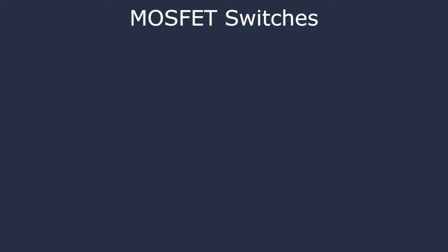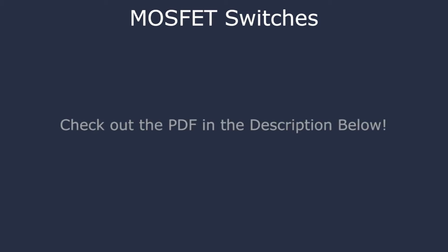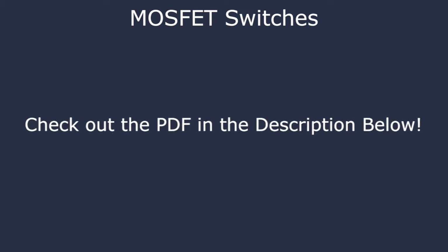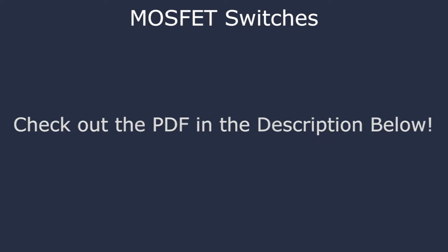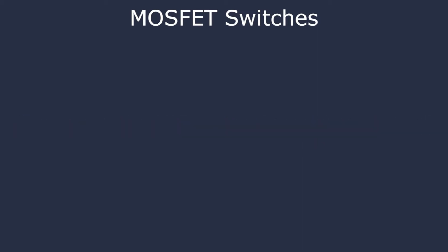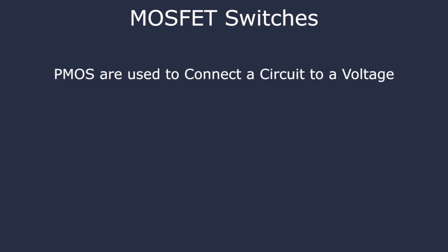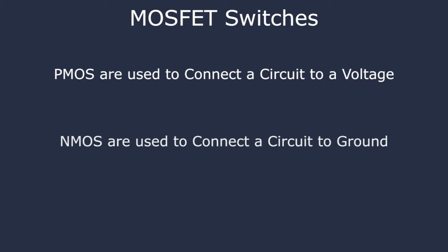We recognize that this explanation may be a little confusing. We recommend reading our lab document, or researching more online for additional help. However, you don't need to perfectly understand this in order to use PMOS or NMOS transistors in your circuit. If you simply memorize that PMOS are good at pulling up to a voltage, and NMOS are good at pulling down to ground, you'll be just fine.